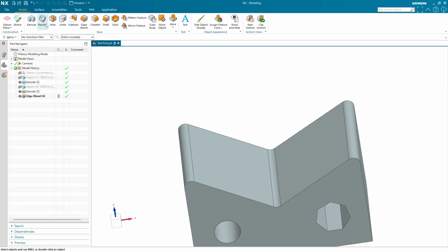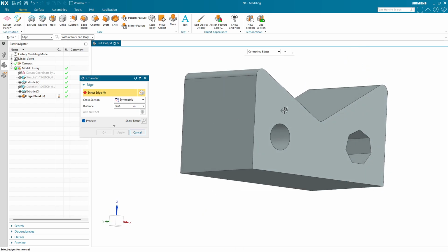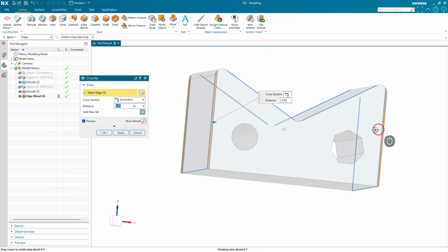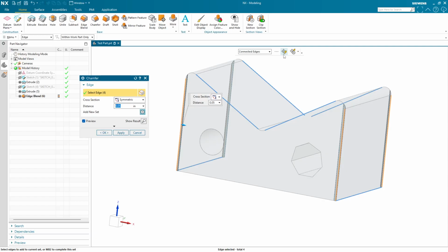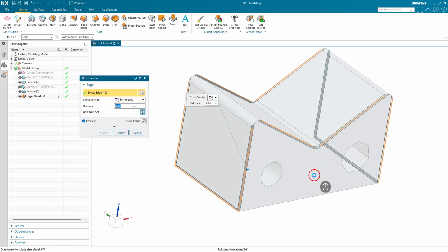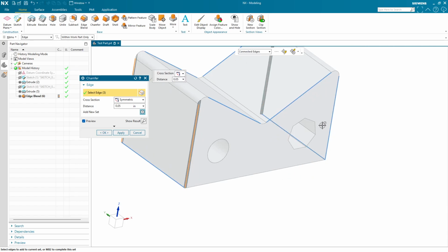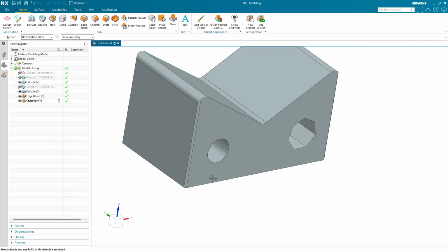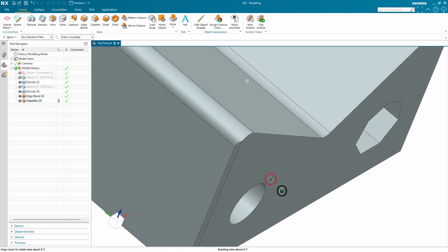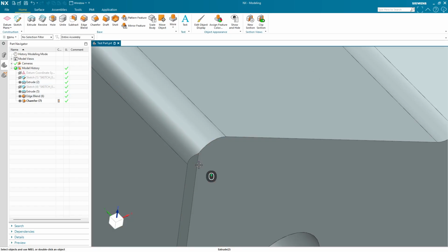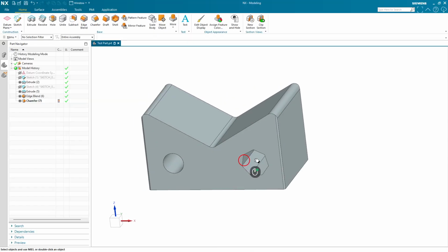Let's chamfer the uprights a little bit. So like these corners right here. So I'm going to chamfer that to 0.05. If you click on select predicted objects, that's everything in the blue. So it would pick everything for you. It's pretty aggressive. I don't really want all those objects. So I'm just going to pick the ones that I do want. On those uprights right there, hit OK. And then I have some nice chamfered corners. Looks a little bit funky. That's okay. We're just playing around.